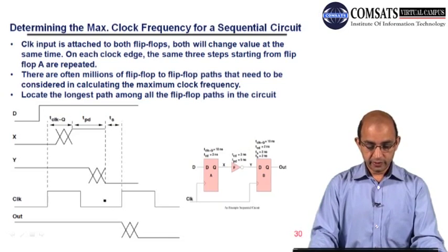TS: Y should be present before this time. This is the setup time TS. So the input must be present this much time before the active clock edge arrives.